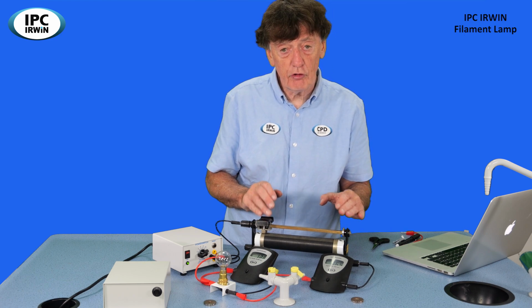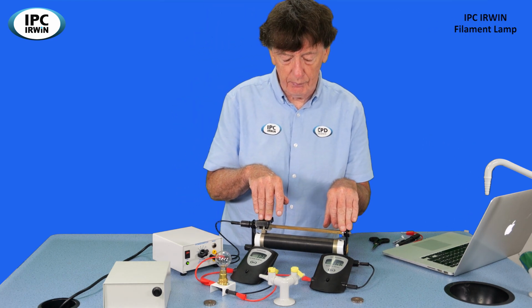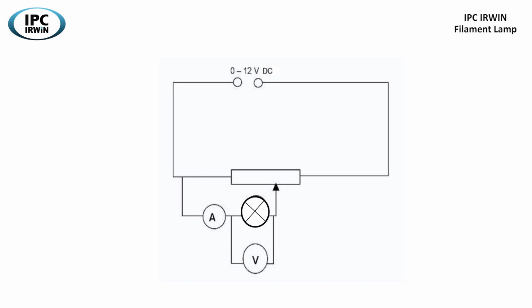That's because we're using this in series as a rheostat. So what I'll do is change the circuit round, and we'll go back to the potential divider circuit that we used in one of the Series 1 videos. So our third and preferred way of changing the potential difference across the lamp is to use the variable resistance in what we call potential divider mode, which we looked at in the previous series videos on electrical circuits.